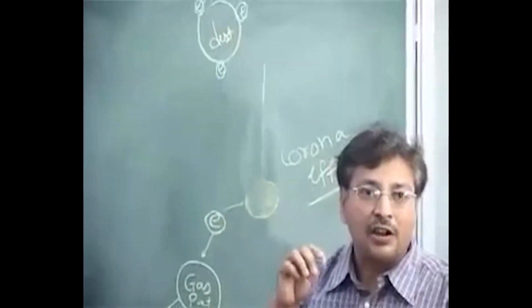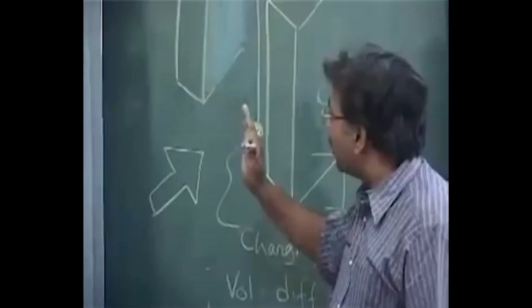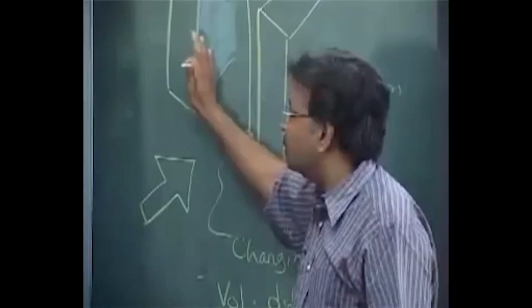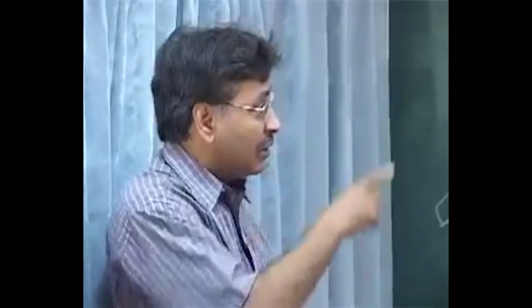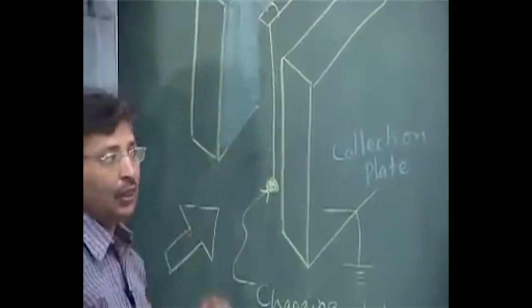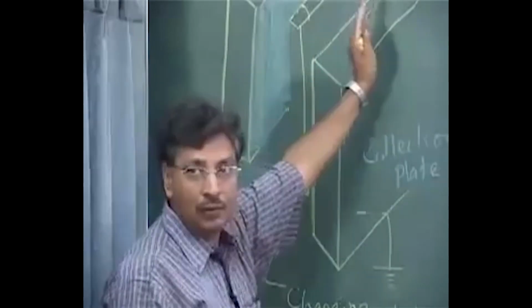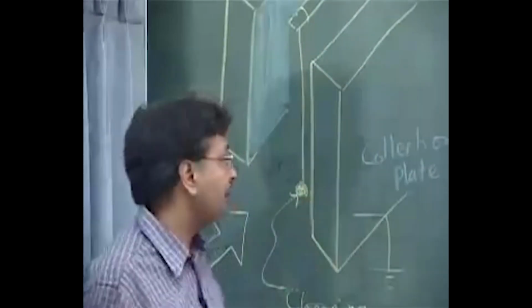Nothing from the inside or nothing at the atomic level, they are just sitting onto this one. As a result, these particles, which were otherwise going straight, tend to have a migration velocity towards the plate. So this is what happens. Now you see the corona effect very close to this thing, and these particles will form a little cake onto this one. So this is the thing, and as we go a little away, the gas becomes more and more clean. We will see this one.